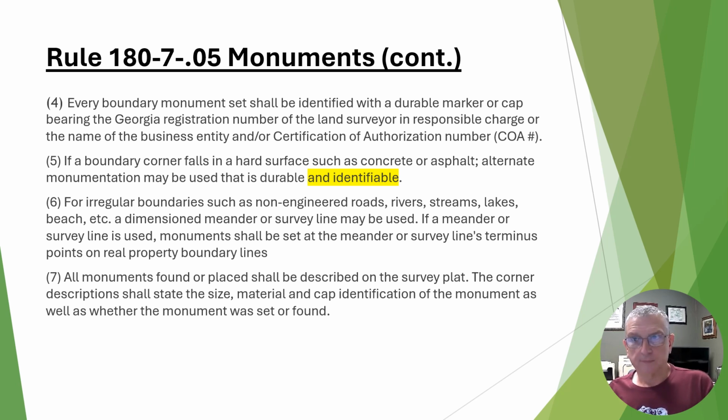Number 7, all monuments found or placed shall be described on the survey plat. The corner descriptions shall state the size, material, and cap identification of the monument, as well as whether the monument was set or found. So to say IPF doesn't get it. If everything that you found was a 1/2-inch rebar and your legend says IPF equals 1/2-inch rebar, you've actually connected the dots and identified it.